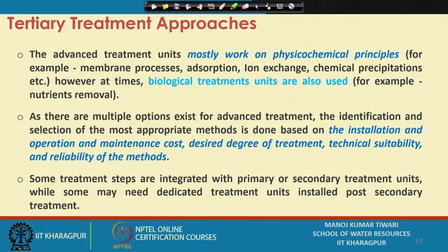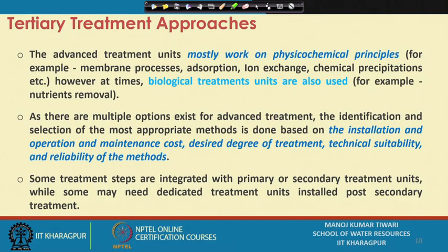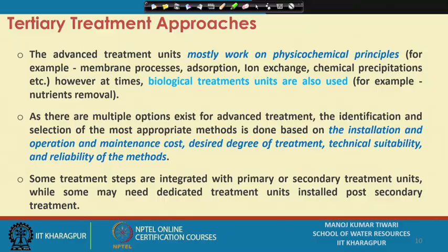Okay. The majority of these advanced treatment units work on basic physico-chemical principles and processes. For example, membrane filtration: straining and letting the water pass through the filter under pressure. Adsorption is a physico-chemical process, ion exchange is again a specific type of adsorption, chemical adsorption, or a physico-chemical process. Similarly, we have chemical precipitation. So, the majority of the processes are of physico-chemical nature, but at times we go for biological treatment units also,